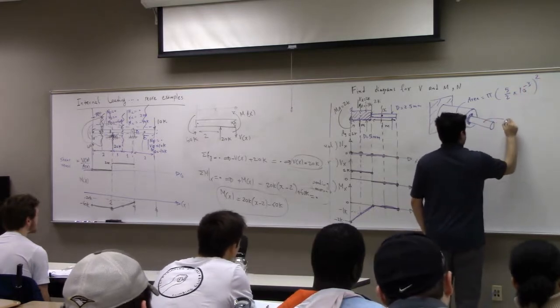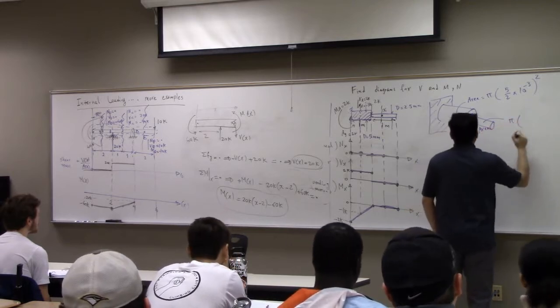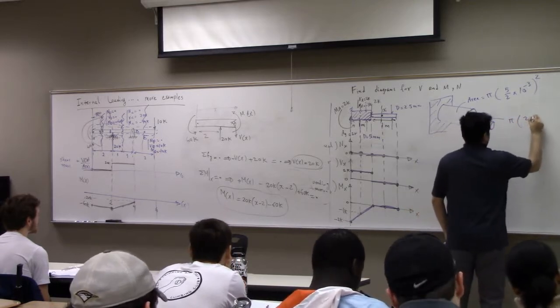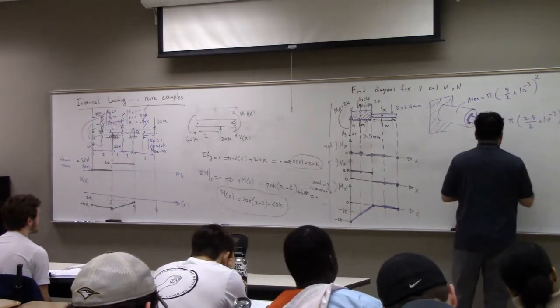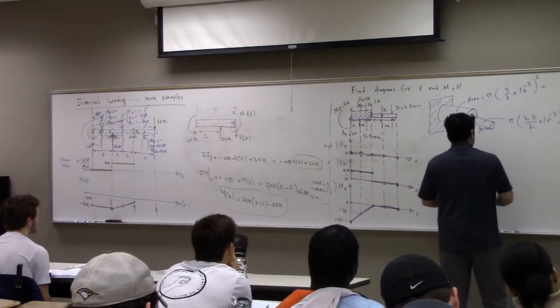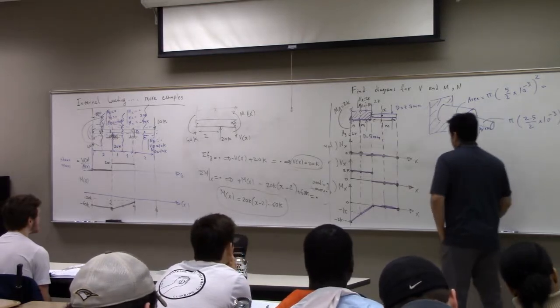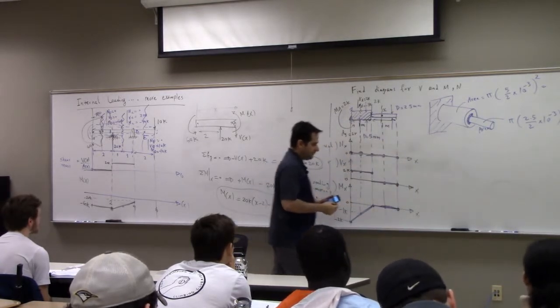And the area here is equal to pi times 2.5 divided by 2, squared. So put it in the calculator, and then also divide this 2K by that. So from here to here, if I want to draw the average shear stress diagram,